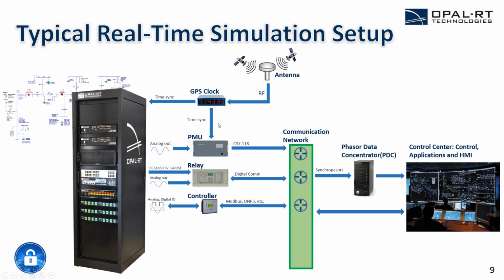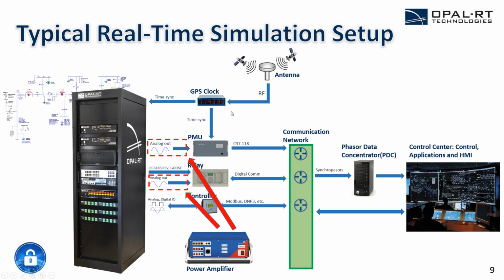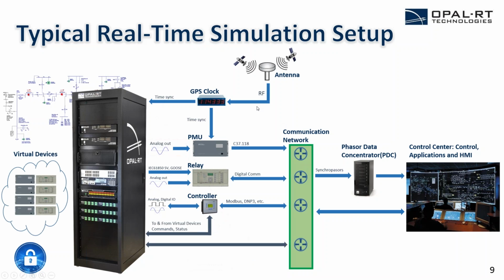And we also require, especially for synchrophasor applications, time synchronization. So a simulator must be able to sync to, for example, a GPS clock. And for high power applications, you can always throw a power amplifier into this loop. And one of the main benefits to this model-based approach, since you are modeling your power system using software, you can actually implement what are essentially virtual devices within your model.